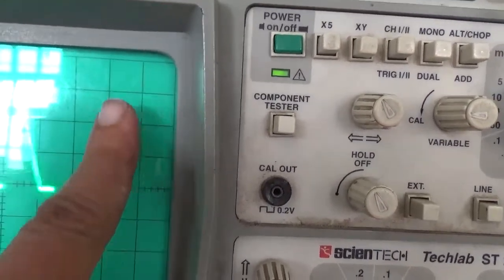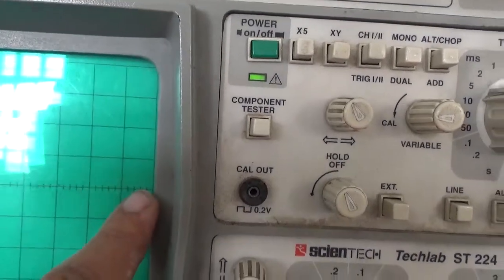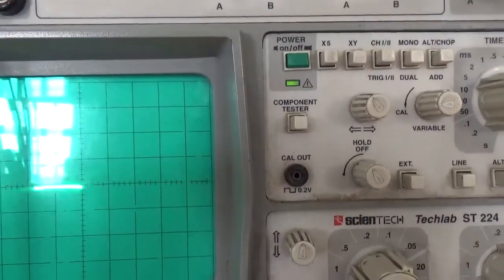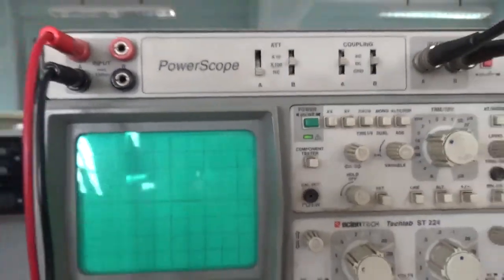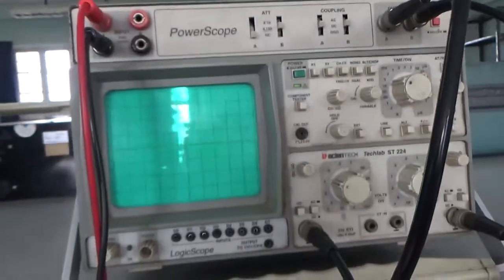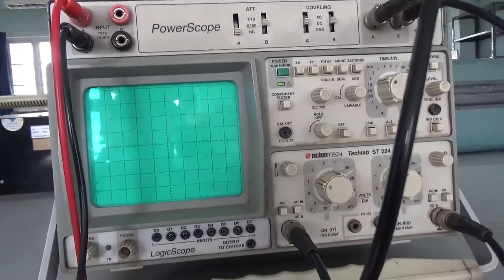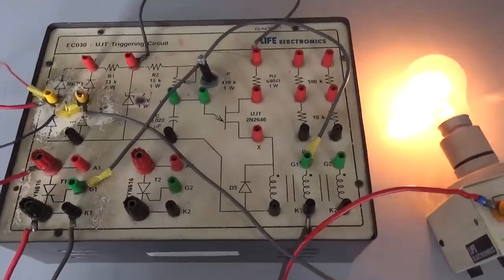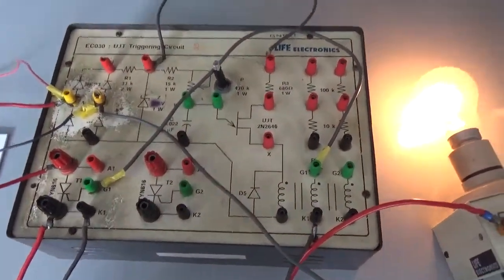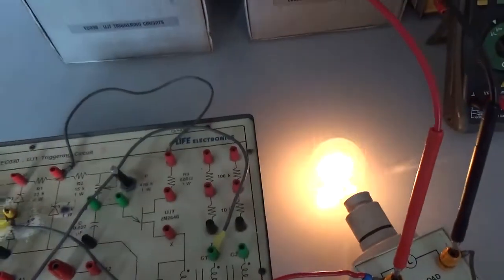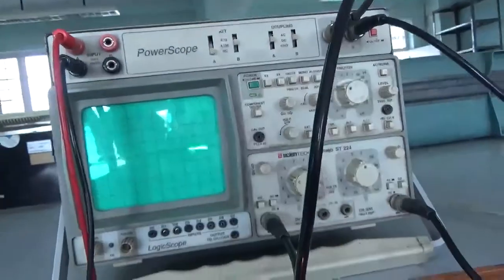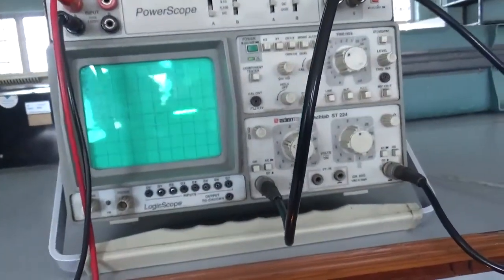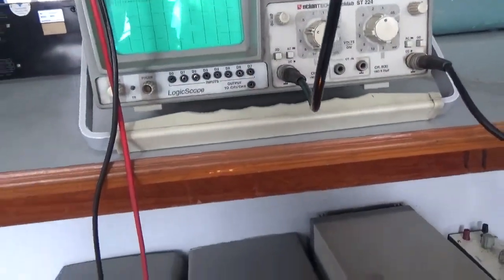Now one complete division is 0, and for one complete division I am getting the output voltage. This indicates alpha equal to 90. This is how we can vary alpha and draw the output voltage for different values of alpha. This is what we are supposed to do in this experiment. First, do the connections, then vary the resistance to set any 2 different values of alpha, observe the waveforms across SCR and load, note them down from the CRO, and draw them on your graph sheet. The third thing we are going to do is measure the output voltage.